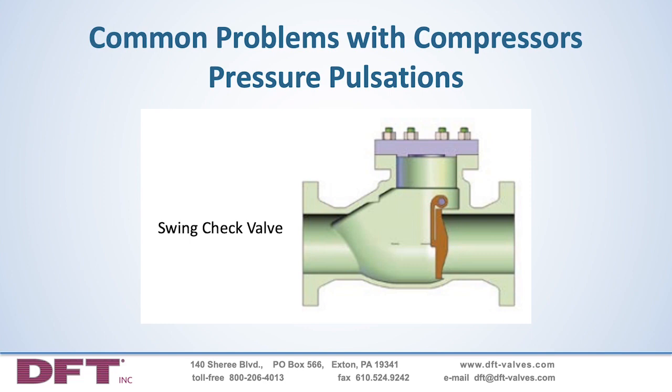Wear of the valve's internal components can ultimately lead to gas leakage and subsequent reduction in output pressures throughout the piping system, as well as back pressure into the compressor itself, which will reduce the compressor's efficiency as well as lead to other serious maintenance problems. High cycling can wear the often used piston check valves and cause extremely high maintenance and eventual failures that then have to be addressed.